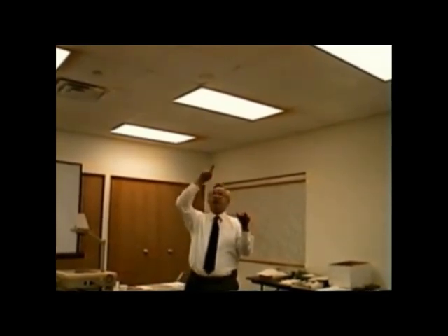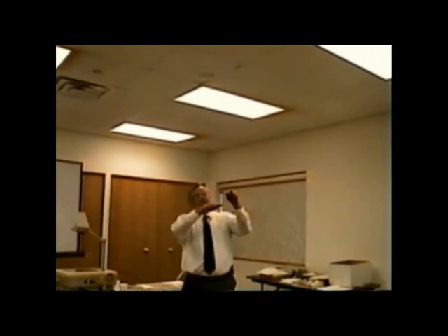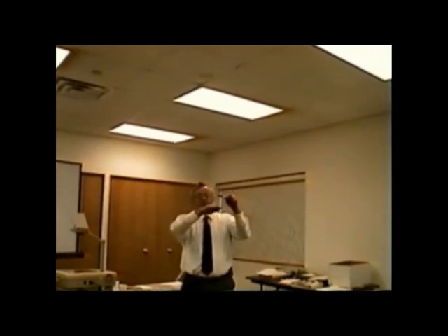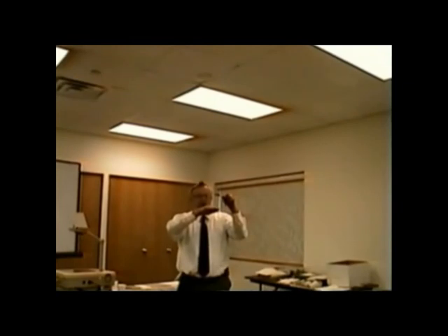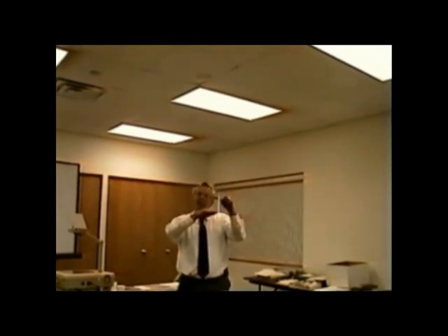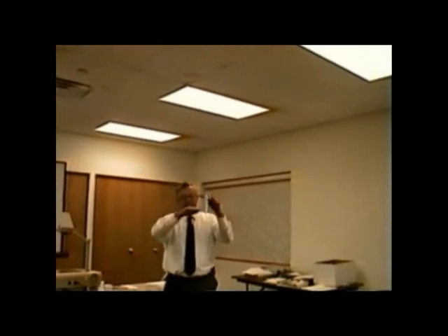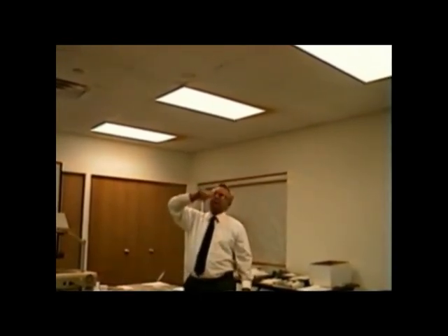So if we put 24 volts, we have AC. When we use this as a conductor, when the fire conducts current, it converts it to DC. So it's not AC microamps, it's DC microamps. And I got to tell you that if you look on a scope, this is really neat.